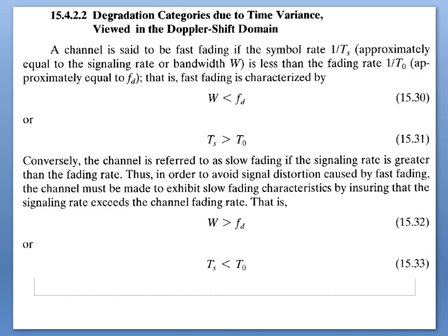The peaking of instantaneous frequency shifts at a time near the deep phase null can take the form of FM clicks or spikes. The above figure shows bit error rate versus Eb/N0 for DQPSK signaling at f0 of 850 MHz. It should be clear that at high Doppler speed, the performance curve bottoms out at an error rate that may be unacceptably high.